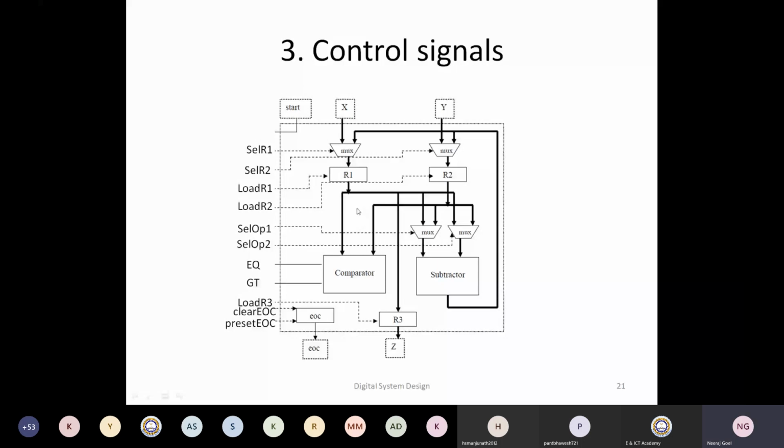Okay, so when we design an RTL, this particular design is also called a register transfer level design, because we know in what cycle we are performing which operations. When we are implementing this RTL, there are various ways of doing it. The way I am doing it is in a more idealistic way, where the data path is represented using data flow, and the control path is represented using behavior. Okay, with that, let us go back to our demo.